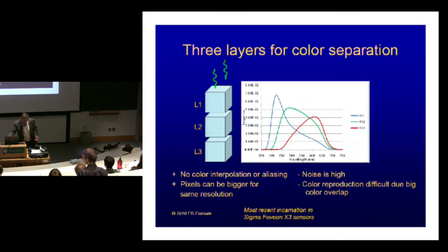One thing people have done, not directly related to small pixels, but related to being more clever, is to consider the absorption of light that comes in and think about, let's make 3 layers in the silicon stack, layer 1, layer 2, and layer 3. And the photons come in, and maybe in the first layer, it's mostly dominated by blue absorption, or blue photons, and the second layer by green, and the third layer by red. And if we plot the response versus wavelength for layer 1, you see that most of its response is in the blue, and for layer 2, it has a big response in the green, which is 550, kind of broad. And layer 3, sure enough, all the blue light's absorbed up here, it doesn't get down here, so there's no response in the blue for this layer, and then it kind of picks up. And we kind of get 3 different color signatures out of these 3 layers.